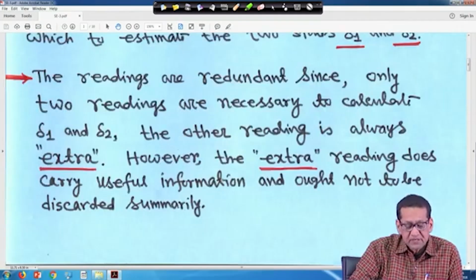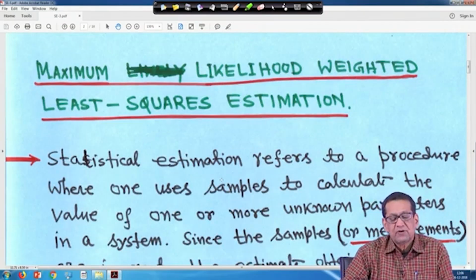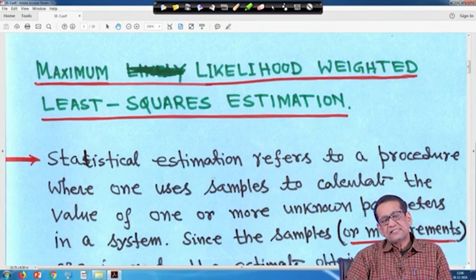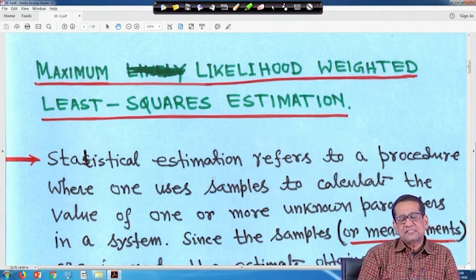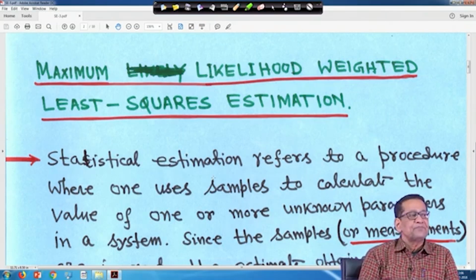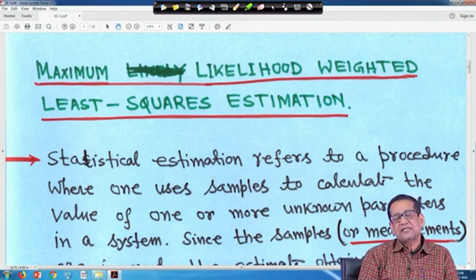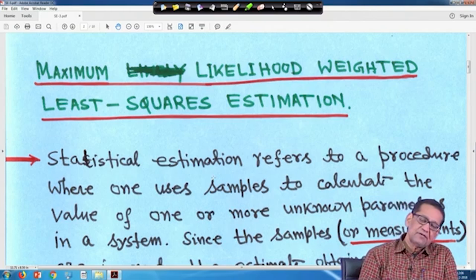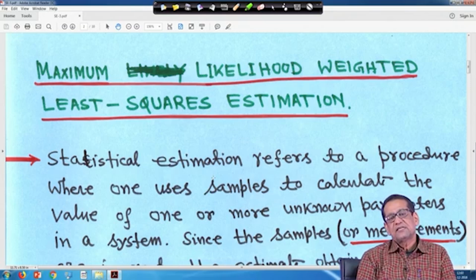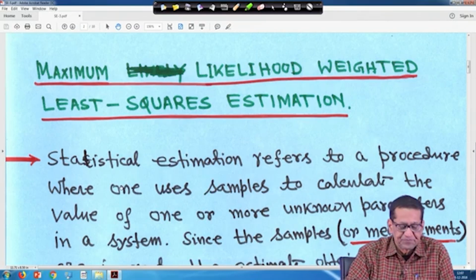So, that is why we will go for a new concept, that is how we can accommodate all these things. For state estimation, we will do static state estimation, but we will see 3 types of cases. One is when the number of state variables is greater than the number of measurements, that is ns greater than nm. Another case is where the number of state variables is equal to the number of measurements, that is ns equal to nm. Another is where ns is less than nm, that is the number of state variables is less than the number of measurements.